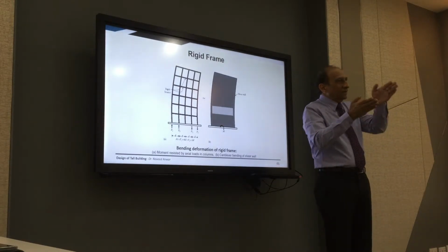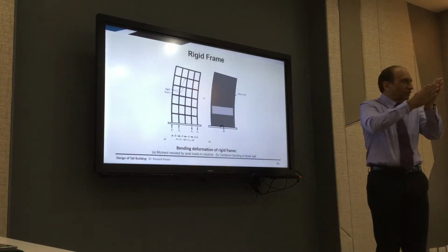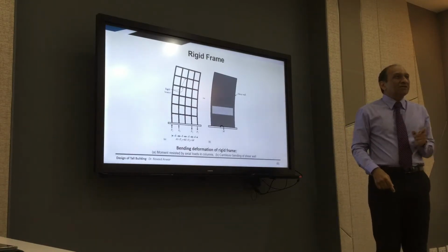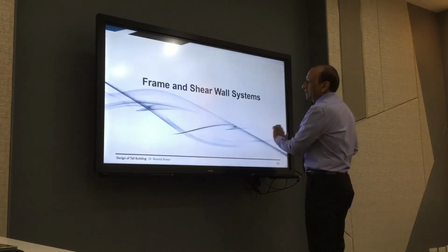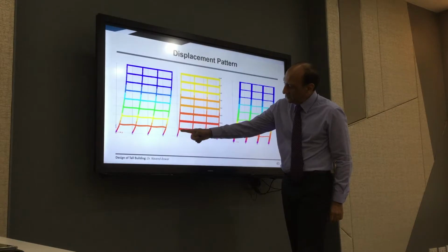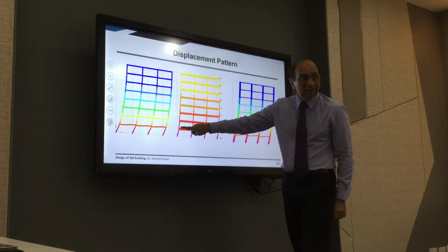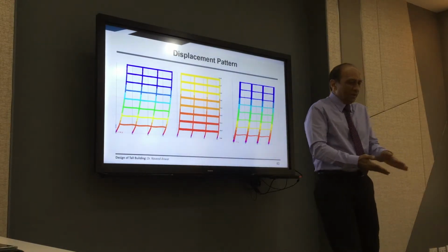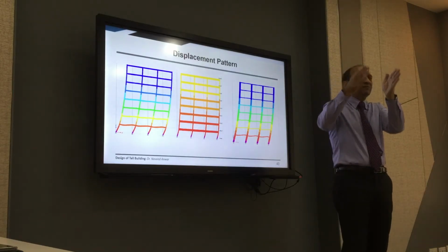And as we go up, the deflection will become large, right? If you have a cantilever, close to the support there will be no deflection. As you go to the tip, there will be more deflection. But a frame is opposite. The maximum deflection in the frame, if you go back here again, is here in the beginning. See? A lot of deflection comes right in the beginning. So frames deform in this way. They deform and then become a little bit straighter because the forces above become small.